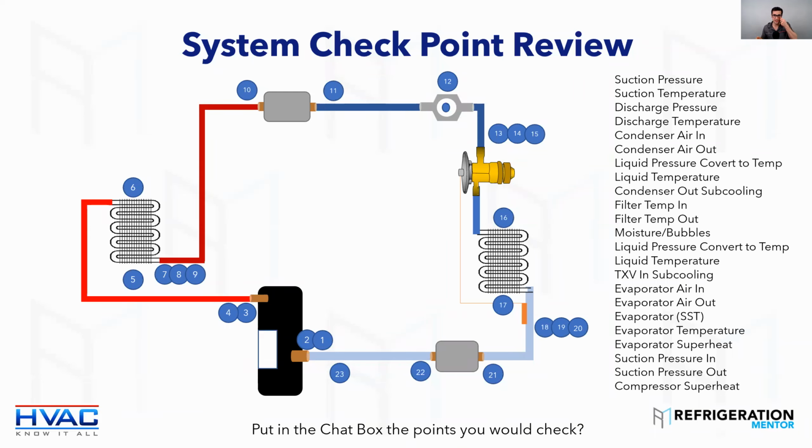Chris Stevens from HVACR videos has lots of good videos on it. And there's a good example in one of his videos I watched. He was going across the roof, and all the pipes are laying across the roof, and he points at the insulation. Look at this insulation. He touches it and it flakes right off. And you know, in California, it gets super hot. So in the middle of the summer, can you imagine the amount of heat that's penetrating this hot roof and being absorbed, and really how much heat it's bringing back to that compressor?